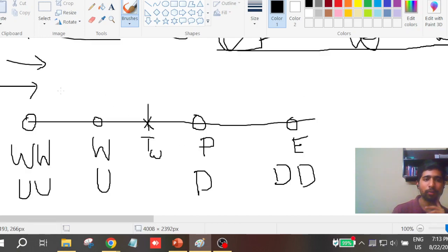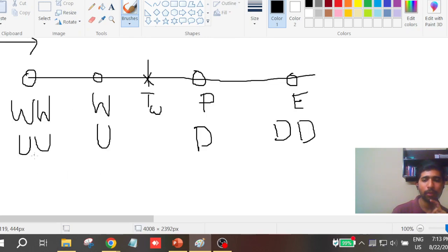So this is the upstream direction because I am assuming that the flow is in the positive x direction. WW will become upstream of upstream, and W will become upstream because I am looking from the west face. So this is my border. Whatever is on the left side is upstream, whatever is on the right side is downstream, because the flow is in the positive direction.